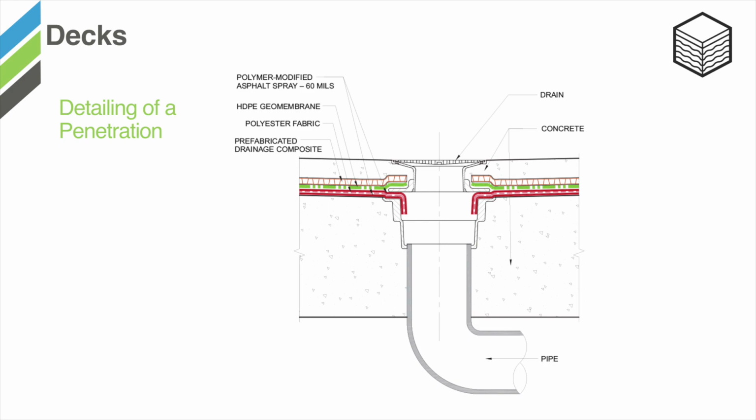Redundant field installed systems, like any other system, require proper detailing. In this case, we're looking at a drain detail. It is important that all drains are properly detailed. All flashing and counter flashing on termination edges are also done in compliance with manufacturer recommendations.